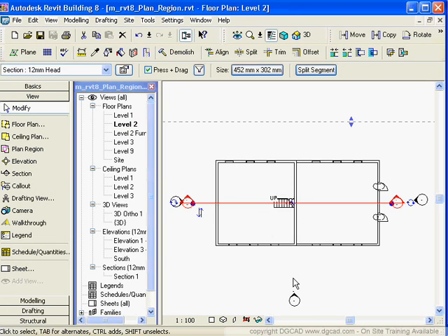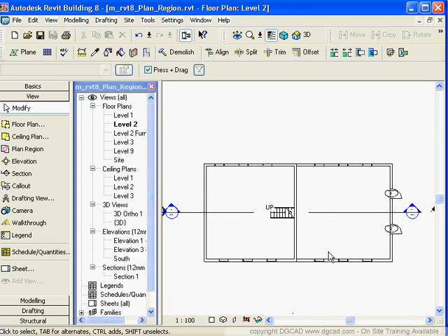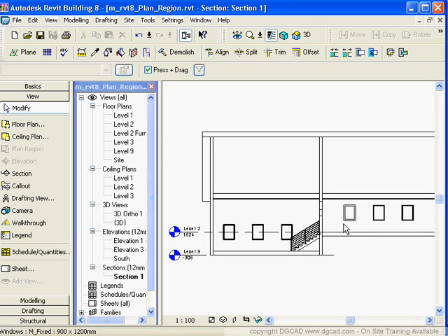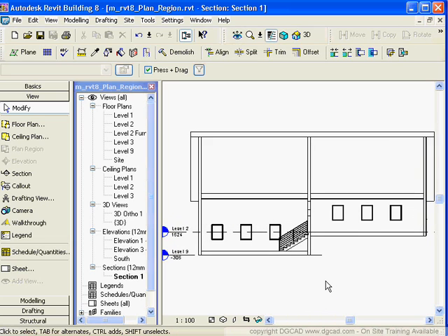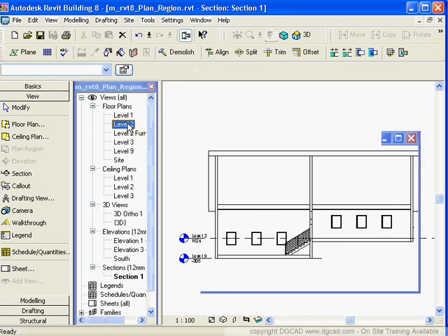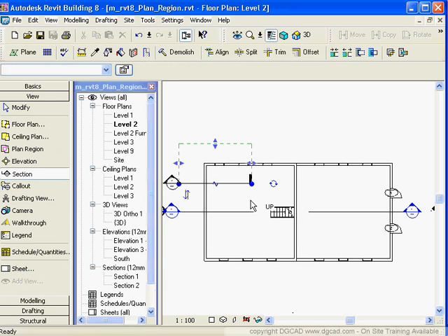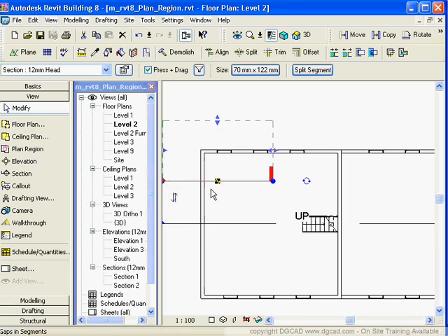So back to our views, elevational views, we can go into a section, which we've got inside of here. Now we can take that section and move it around. We can hit the break button, and it'll create a break inside of there if we grab those points. Double click on here, and we can have part of that object line hide when we want to in the section line. Again, we can move this along.